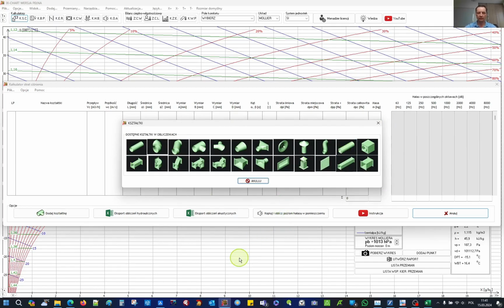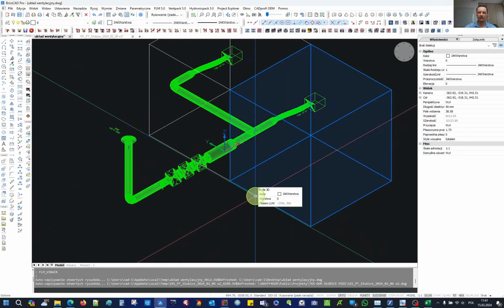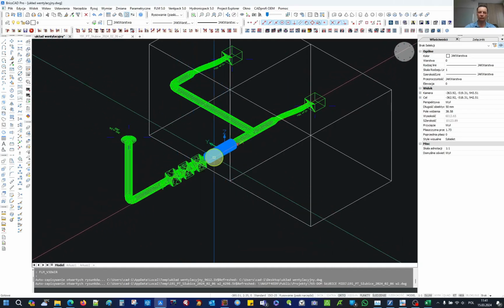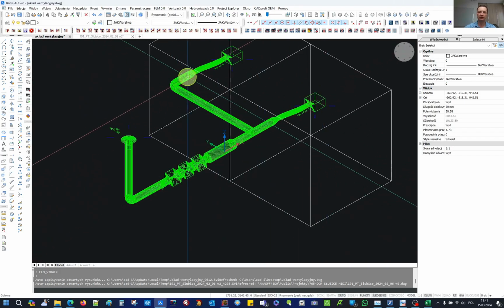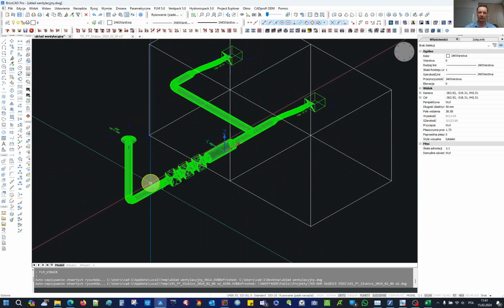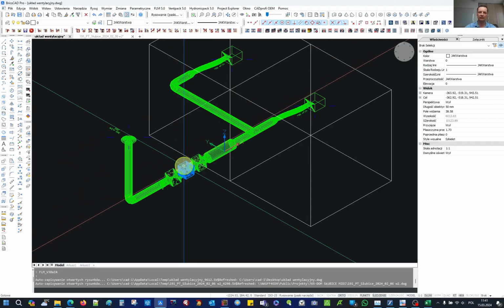For the purpose of this presentation, I prepared a small ventilation system diagram which shows a noise source in the form of a fan, the noise suppressor as a damping element, and the duct system delivering air to individual rooms. This system is essentially built from fittings with a diameter of 200 and 125 millimeters when supplying air to the diffusers into the rooms themselves, which I will soon show how to carry out.